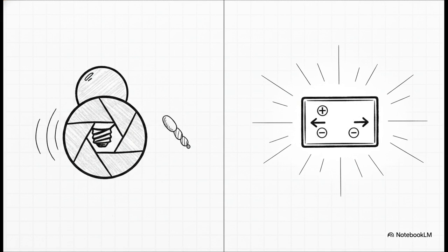For LCDs, make it crystal clear that they do not generate their own light. Instead, they act as optical shutters, controlling an existing backlight through molecular orientation. For LEDs, forcefully state that they generate their own light directly through continuous electron-hole recombination at a semiconductor junction. Just remember, one is a clever mechanical shutter, and the other is literally a tiny quantum light factory.